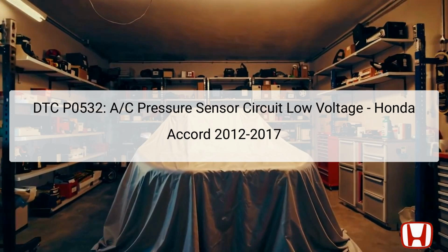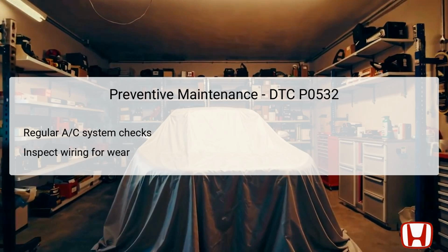Proper understanding and addressing of this code can lead to effective troubleshooting and resolution, ensuring a well-functioning air conditioning system, vital for driver and passenger comfort. To prevent future occurrences of DTC P0532, implementing a routine preventive maintenance schedule is beneficial. This schedule should include regular checks of the air conditioning system to ensure it is functioning efficiently. During these checks, it's important to inspect the AC pressure sensor and associated wiring for any signs of wear or damage that could lead to future issues.